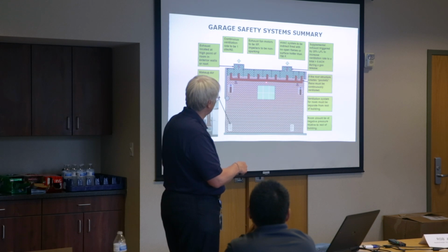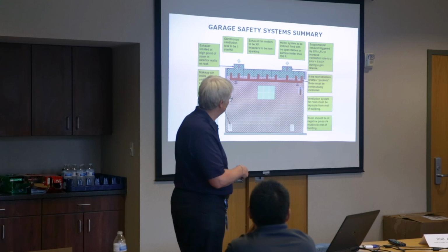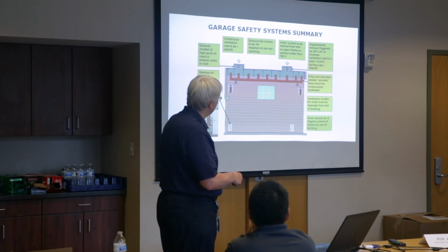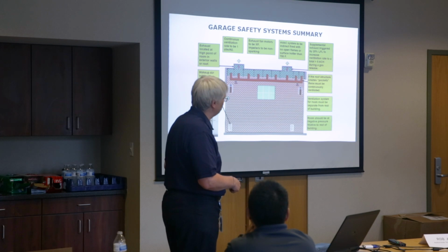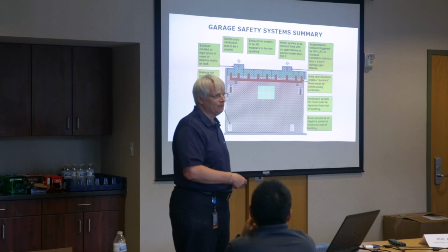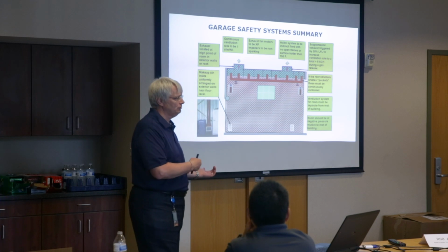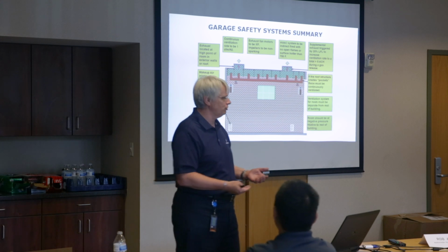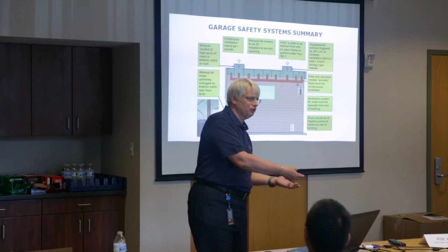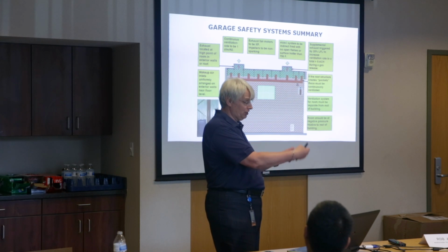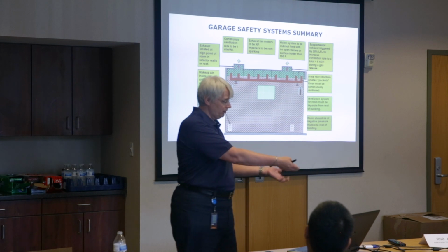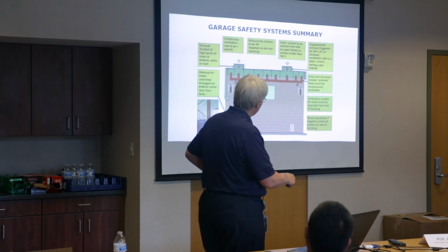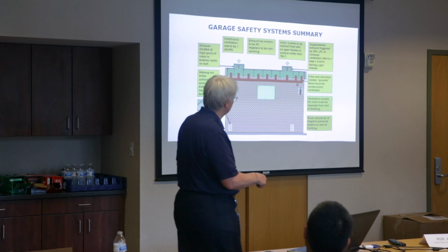So you can see we've got ducting that's poking up into each of those pockets. It's a diagram, but the ventilation system for this room must be separate from the rest of the building. We don't really even want to connect ventilation between building spaces. For example, with your maintenance garage, it's best to have a separate ventilation system for maintenance versus the parking area. And the room should be at a negative pressure relative to the rest of the building.